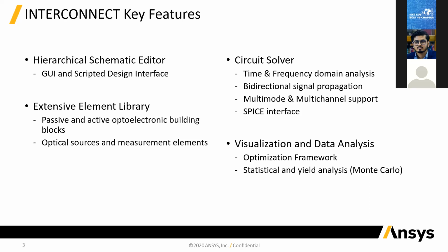And that's something that Monte Carlo analysis allows you to do. When you run your simulation, the solver will randomly change the behavior of each of the building blocks, and then run multiple simulations, and then at the end give you a report as to what percentage of the circuits that you ran simulation for are performing according to spec, and that way you can get the yield of your circuit in the end.